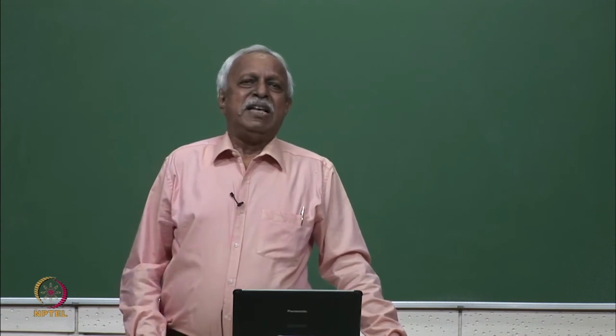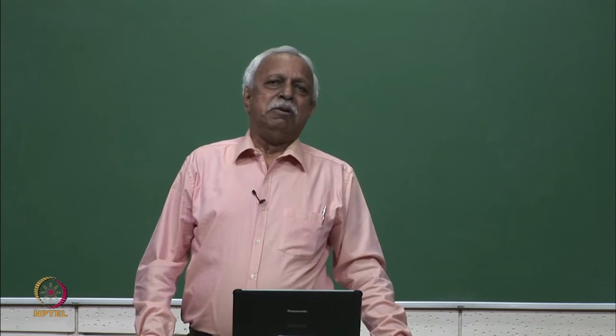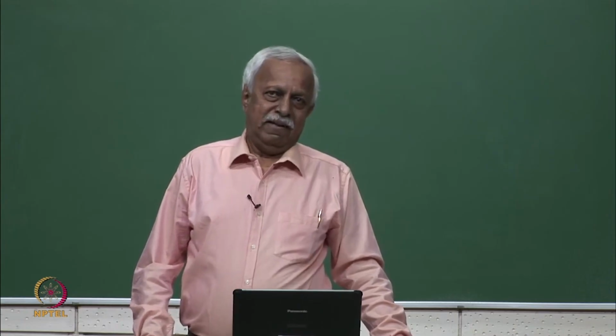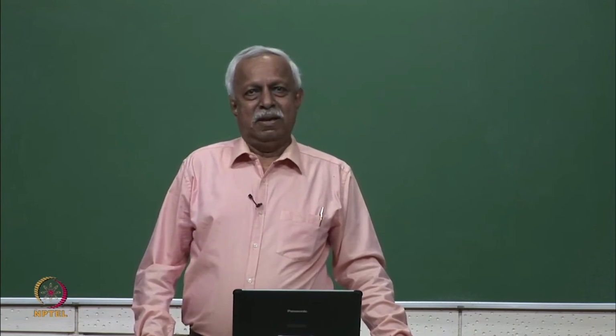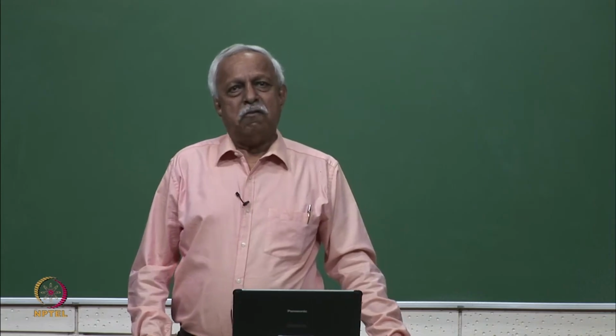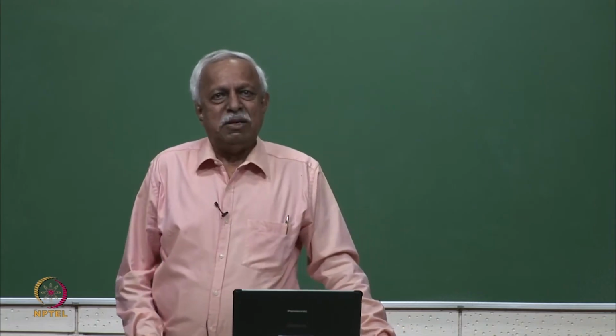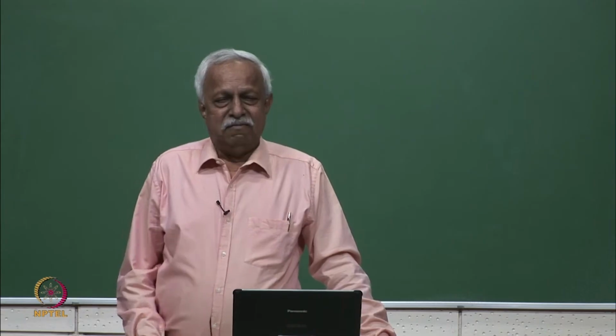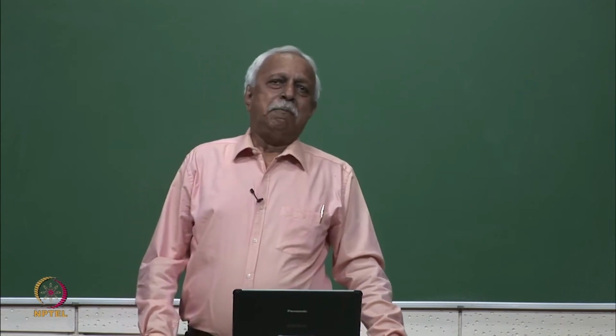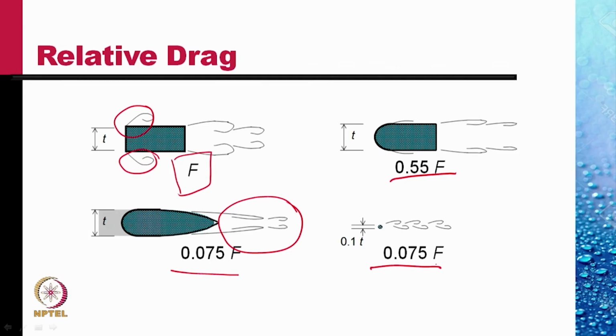they used biplanes which were strung with a lot of cables. Those cables contributed to a lot of drag, even though those cables were very thin. In fact, later on, they started replacing these cables with aerofoil shaped cables, which had a cross section like this, so that the drag could be reduced.